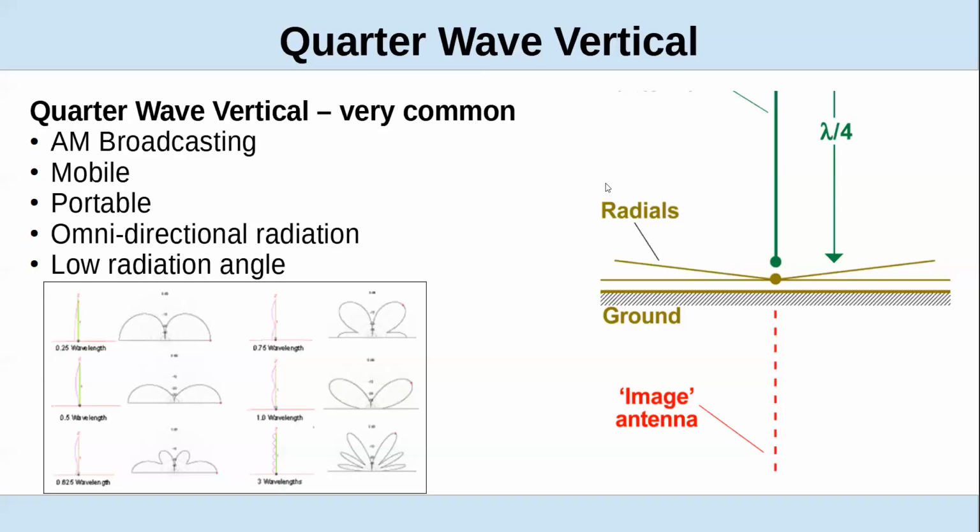But after probably about 7 or 8 elements, the difference. Yes, diminishing returns. Actually, they claim it's probably not worth it after 5. Yeah. You're better off stacking them, and you get 3 dB by putting 2 of them up. And it takes probably 10, 12 elements to get that 3 dB just by adding them. And plus, you get a very long boom.